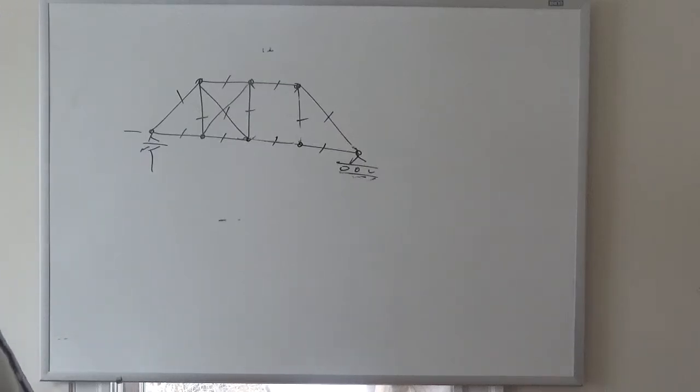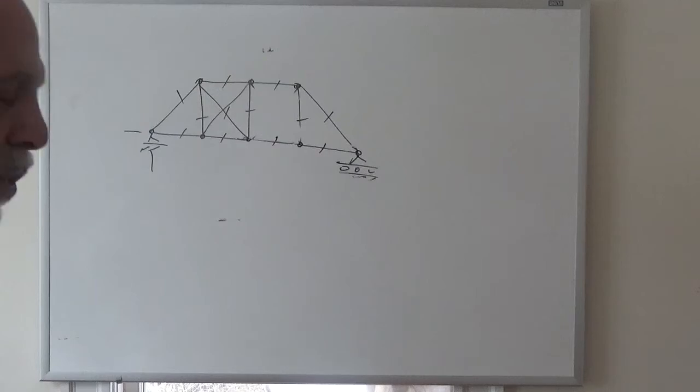Therefore, instability when you draw in a structure is an issue that, well, if a certain count doesn't satisfy some limits, like in the case of the truss, if 2J is more than B plus R, you can say with 100% certainty that the truss is unstable because you have too many equations for the number of unknowns. However, if your count tells you that the structure is either determinate or that it's indeterminate to the degree 1 or 2 or 3 or whatever, there is always the possibility that the structure is actually unstable, okay?